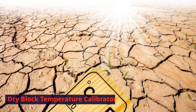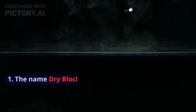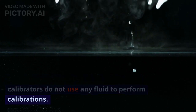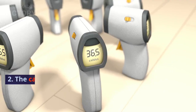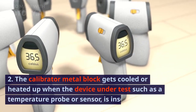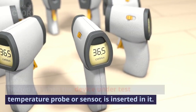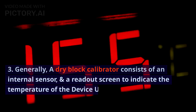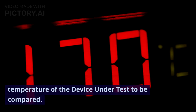Dry block temperature calibrators. 1. The name dry block implies that these calibrators do not use any fluid to perform calibrations. 2. The calibrator metal block gets cooled or heated up when the device under test, such as a temperature probe or sensor, is inserted in it. 3. Generally, a dry block calibrator consists of an internal sensor and a readout screen to indicate the temperature of the device under test to be compared.